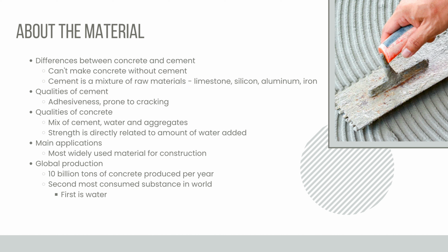Adding water to it holds it all together until it hardens. And the strength of the concrete is directly related to the amount of water added. So adding a lot of water will make the compound easier, more malleable to use, and adding less water, which makes it less workable, will make the finished product stronger and more durable.